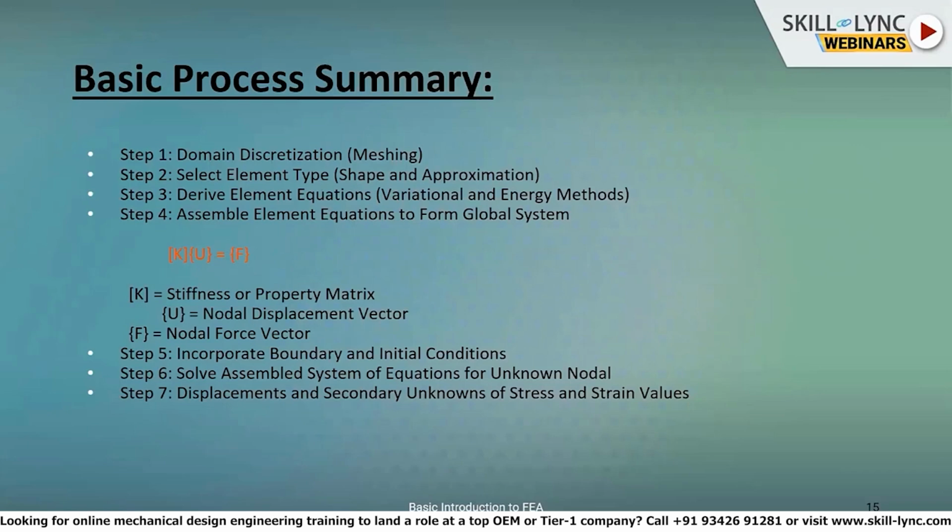The sixth point will be to define the boundary conditions to remove all free body motions, because when we have the stiffness matrix, it will be without boundary conditions. What does it mean? It will have rigid body motion, since you don't have any constraint. So when we apply the load, the body will move as a rigid body without any deformation or strain. In that case, the software cannot solve that equation.